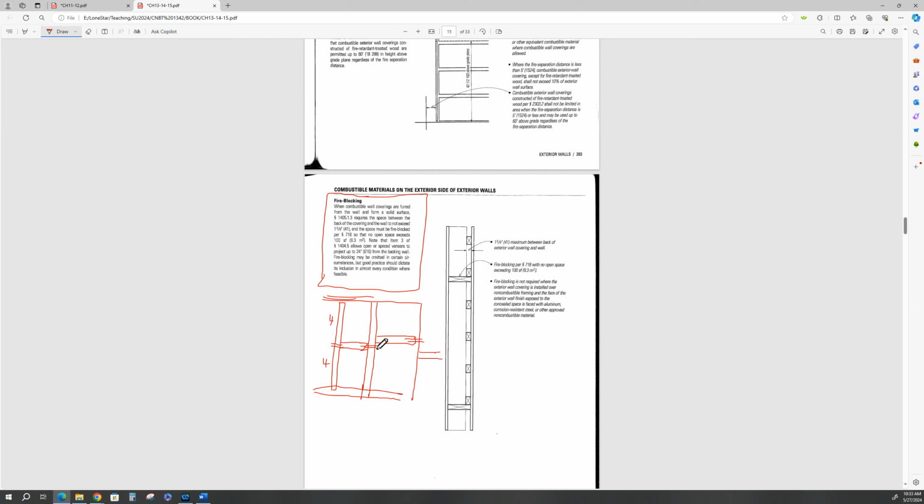And this is 1.5 inches, so you'd offset this maybe a couple of inches. So this is going to be 4 feet plus, and this is 4 feet minus, but it all averages out to 4 feet. So now you've got a column that's half the length, and it'll carry more load. It'll also be more resistant to shear loading coming in this direction.